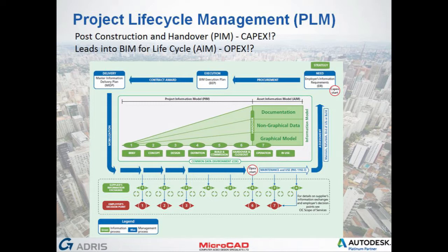So at each of those critical stages inside the project design and construction, you would have a data drop, which is just to drop off the information to everybody involved, and have a fixed point in time for that project and a decision point for that part of the design. This is more the CIC system at the bottom there, obviously working with the RIBA plan of work.